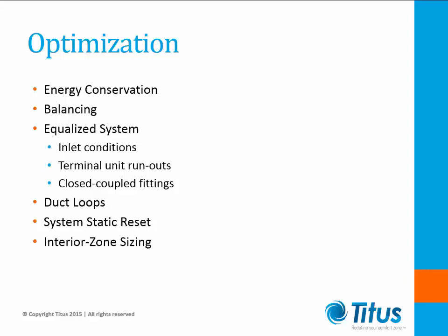Loop ducts are a good tool to minimize both installed ductwork and energy usage. By looping the ductwork, the system can move the air with the diversified load, like a skin load, around the building as the load changes. If separate runouts were utilized per exposure, or some combination of the exposures, the ductwork would have to be sized for the sum of the peaks, and the runouts would require greater pressure to fill them year-round. With a loop duct, allowing air to transfer from both sides of the duct to wherever the design point was at any time of day, you will decrease your total energy usage.